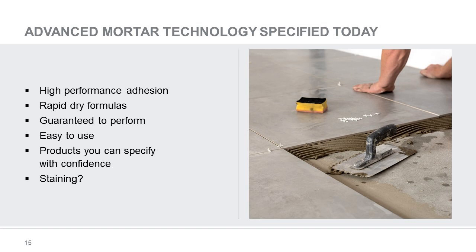Some products will meet and exceed the standards, but are also formulated to provide specialist solutions for natural and agglomerated stone. Some natural stone and agglomerate stone tiles, such as those based on marble and limestone, are moisture sensitive and prone to water staining and warping. This is important to consider when specifying the mortar, rapid drying technology mortar, or epoxy.